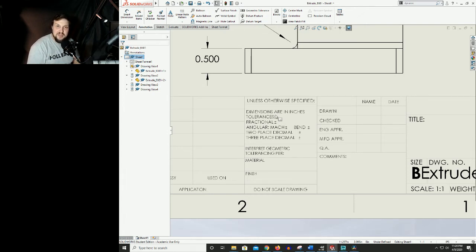All right. So in that case, we would give this part a tolerance on the low side. We would say, okay, we're aiming for 3 inches, guys. But let's say you hit 2.985. That's 15 thou, or 0.015, short of what we're aiming for. That's okay. You can do that. So in that case, our tolerance would be minus 15 thou, plus 0. You can't go any over. You can go 15 thousandths short. So that's a tolerance in a nutshell.